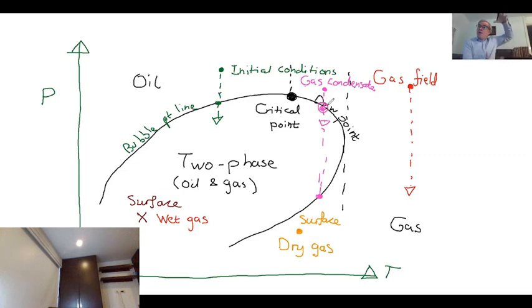So if you've got your well and you're trying to produce very rapidly, you've got a very low pressure here. So what you do is you actually restrict the pressure. You try and keep the pressure at the producing well above the dew point. Okay, so you sort of kick back a bit on production. You then vaporize all the oil, and actually you find then your production rate goes back up again. That will work for a bit, but it doesn't work forever.